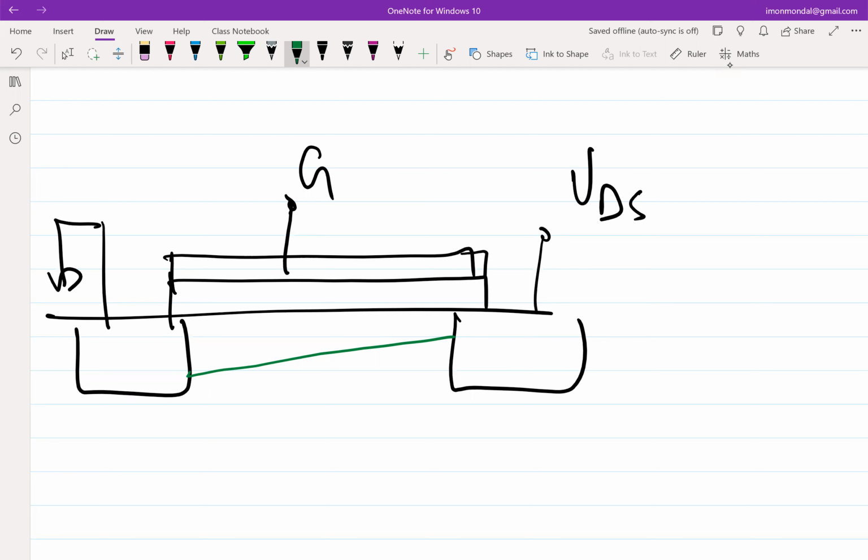So if I concentrate on the charges in this channel and the mobile charges underneath, where do you think the mobile charges will be higher? Mobile charge is a function of the oxide capacitance times the voltage across the plates. Oxide is the same for those slivers. Gate voltage is the same for both slivers, but channel voltage is different, because channel voltage has tapered from drain to source.